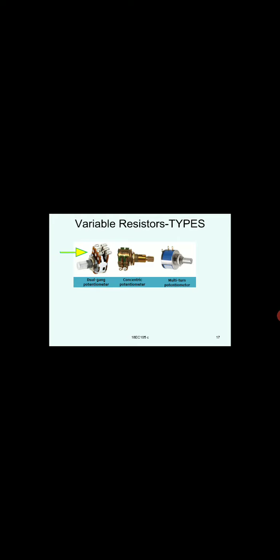And even in industry sometimes when you want to control two channels, there will be two concentric potentiometers, as you can see in the second figure as well. Even that is the same, which is called a concentric potentiometer. Parallel to one shaft you attach two wipers, and they rotate on the tracks.